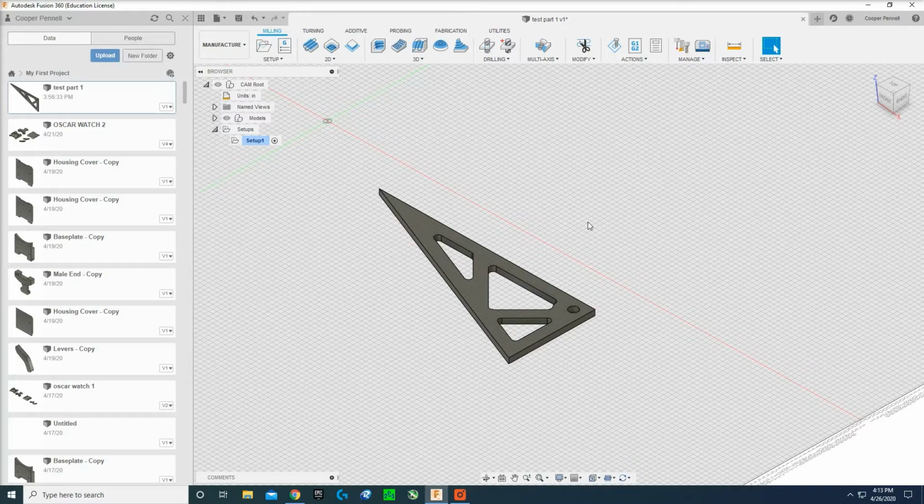Machining is actually a lot more difficult than you think it is. You may create a tool path in Fusion that looks great. You do the simulation, which I'll tell you how to do later, and everything looks great. Then you go down and cut the piece on the router, and it vibrates horribly, and the cut is really ugly and not what you want. So just keep in mind that the cuts you draw up in this manufacturing software aren't necessarily going to be how the part comes out in the end, and there's going to be a bit of a learning curve.